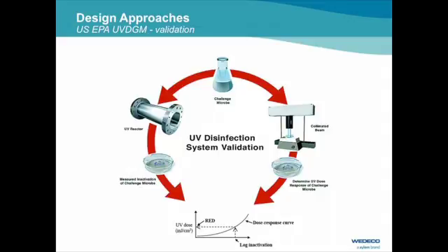And you determine the log reduction. And then from the log reduction, you go to this dose response curve. And then you can determine the UV dose.